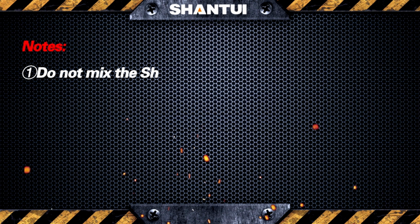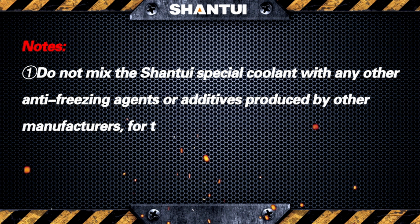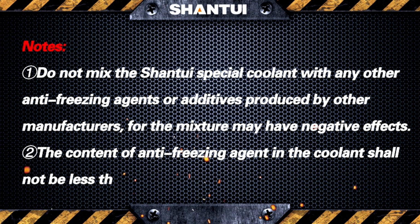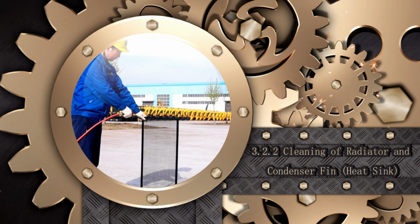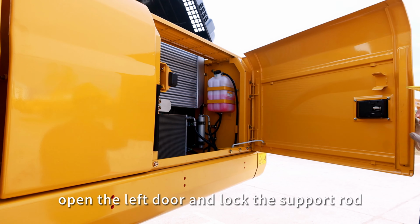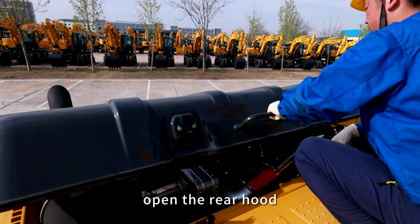Notes: 1. Do not mix the SHANTUI special coolant with any other anti-freezing agents or additives produced by other manufacturers, for the mixture may have negative effects. 2. The content of anti-freezing agent in the coolant shall not be less than 50%. Cleaning of radiator and condenser fin, heat sink. Steps. Open the left door and lock the support rod. Open the rear hood.